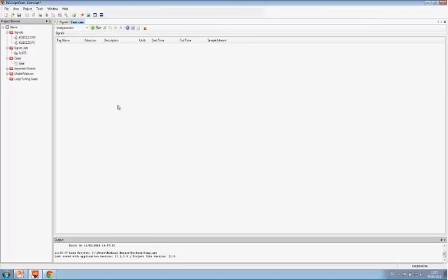Now first I have to select my independent, or I have to select my inputs, and I can select the signals by dragging them on this pane. So now for independent, I have selected the output of the controller. Now for my dependent, or my output, I will select the measurement, of course. Now because this is a ramp, I have to tell AptiTune this is a ramp signal, so I will make this ramp true in this case.